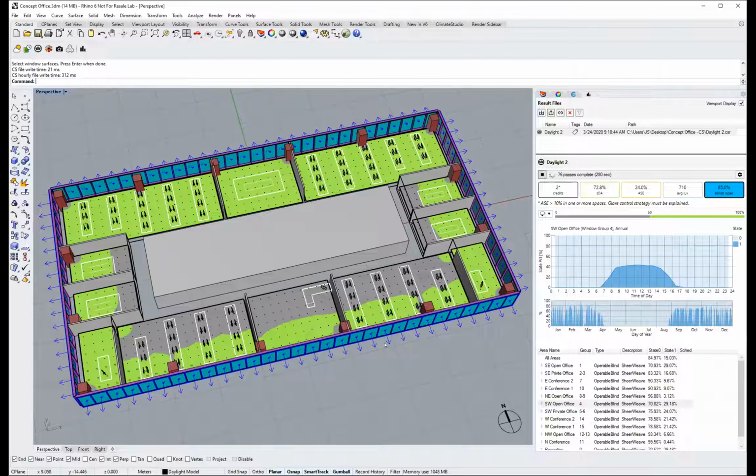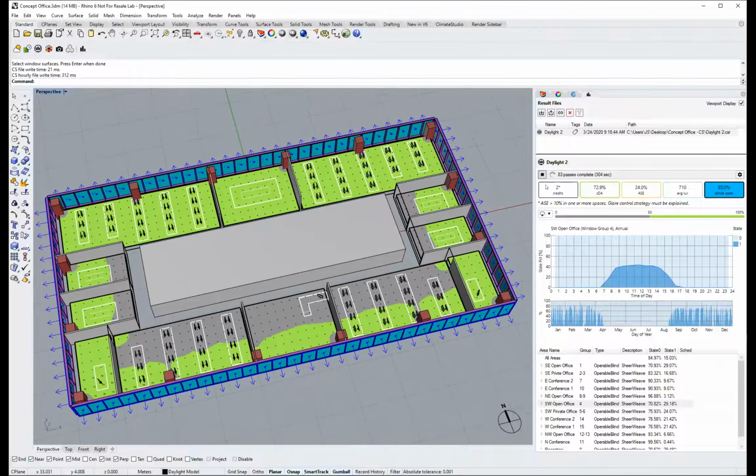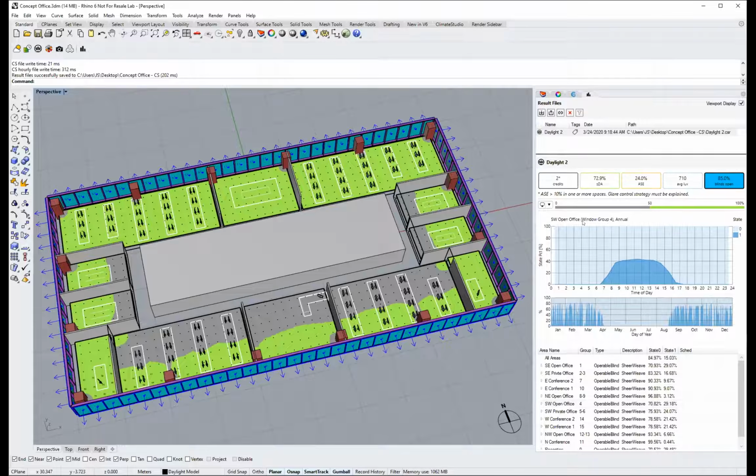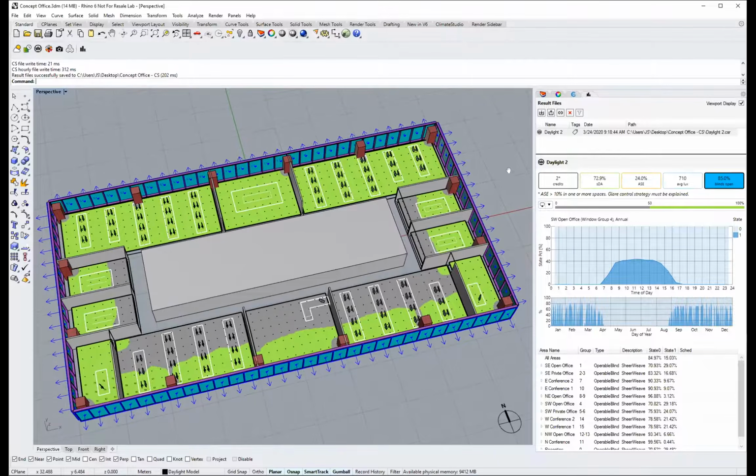As I mentioned, the idea here is that in concept, we can play with other facade design options. It probably shouldn't surprise us, if we're familiar with daylighting, that a fully glazed facade is not the best idea, even though initially you might think more glazing, more light. There's obviously more nuance than that. So as with the point in time workflow, you can see these numbers have actually stopped changing, even though I keep running passes to make the result more and more accurate, so we can stop this at any point. And now I want to look at some other design options.